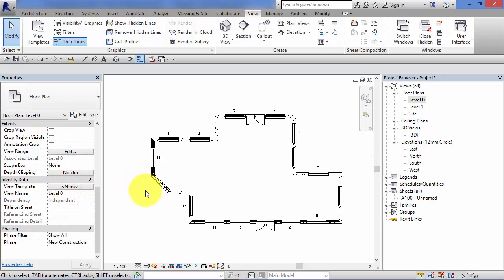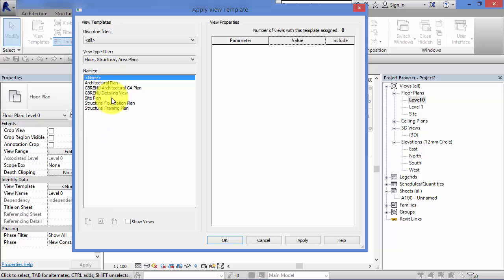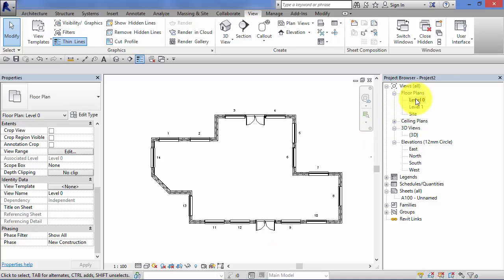So in your Revit template, your RTE file, you would go to your default views, you would look at their properties, and you would choose an appropriate house style, if you like, a view template that you've set up and configured, so that that particular view, let's say a floor plan, when it's used in a new project by a member of staff, actually has your own house style in terms of how the graphics are presented. That will ensure uniformity in terms of presentation across all your projects in the office.